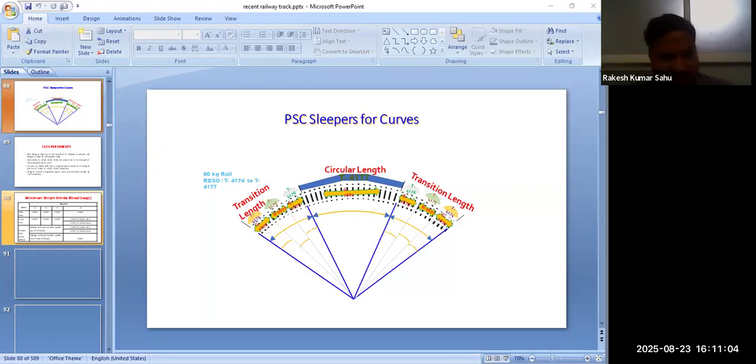It also absorbs some vibration due to cyclic loading, that is dynamic loading, and due to shaking of the entire track assembly, the fastening gets loosened. Also ballast packing below the sleeper gets loosened, and toe load of elastic rail clip also gets lost. The entire track assembly gets disturbed and wear and tear of the rail occurs.